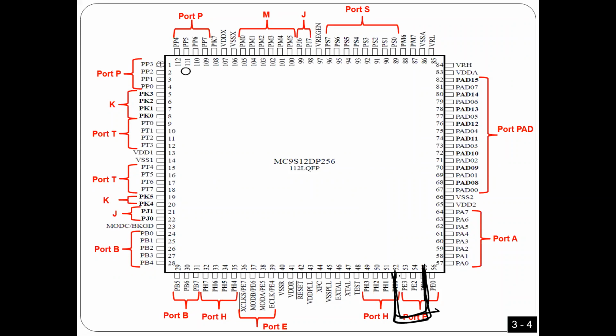way. Okay, between, for example, you can use BH0, you can use BH1, BH2, or BH3. You can use any one of these. You remember? Okay, so if you use BH0, you have to connect wire this way. If you connect an external wire between here and here, is that okay, guys? By doing that, every time you press a button, here on this pin, you are going to generate a signal like this one. And because of this wire, this signal is going to come to IRQ to make interrupts every falling edge.